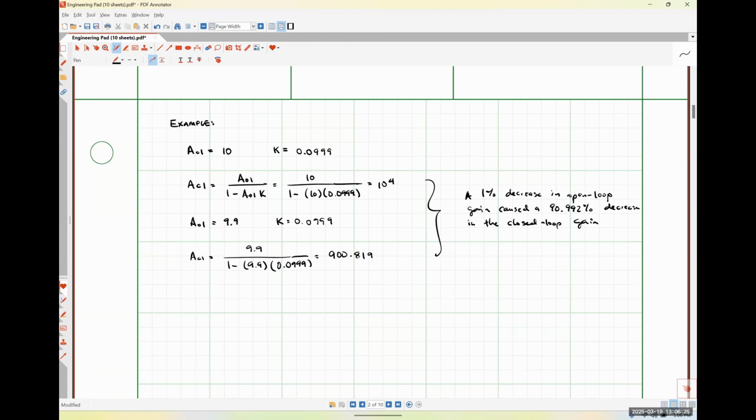So we will generate square wave oscillations that we can use to control the timing of things. And the timing of how quickly it oscillates between VCC plus and VCC minus is dependent on the components that we choose to connect to that positive feedback op-amp network.